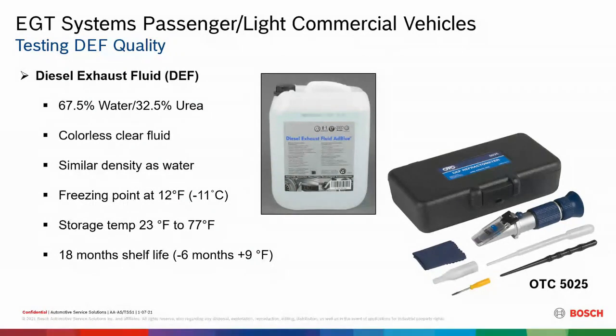It does change the freezing temperature. As I mentioned earlier, water freezes at 32 degrees, where we have this at 12 degrees. Water turns to slush at first. It doesn't freeze solid right away, and then it goes to its solid form. The same thing happens with this DEF fluid. It will freeze completely solid during cold temperatures for a certain length of time. Storage temperatures, they recommend between 23 and 77 degrees Fahrenheit.